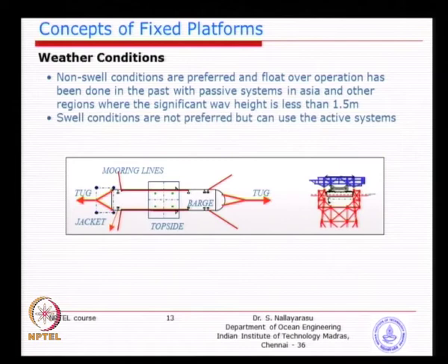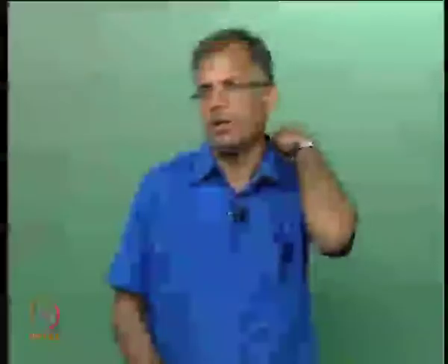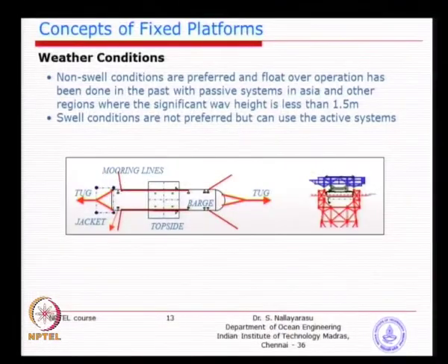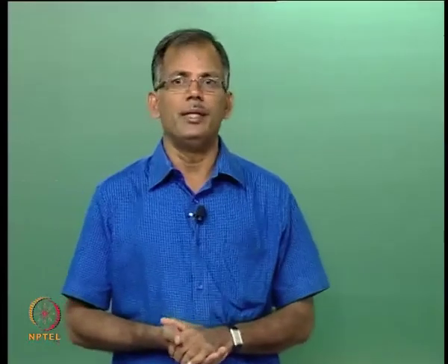One of the biggest problems is swell conditions. I think when you study your hydrodynamics course, you will be introduced to long period waves, which are a potential threat to any installation. Basically, the response of floating systems will be abnormally high, especially for ship shaped vessels. If you have long period waves, even if the wave height is smaller, the response will be larger, and sometimes may go into resonance, especially for ships.